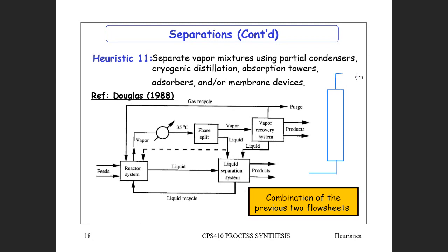And by the time it comes out there, you've got only the gases without that substance that you're trying to recover. Trouble with adsorbers is that you have to have two so that you can switch the process stream from adsorbing to the next one, and then you can desorb by reducing the pressure or increasing the temperature of the whole column. Right, let's have a look what Gareth wants to ask.